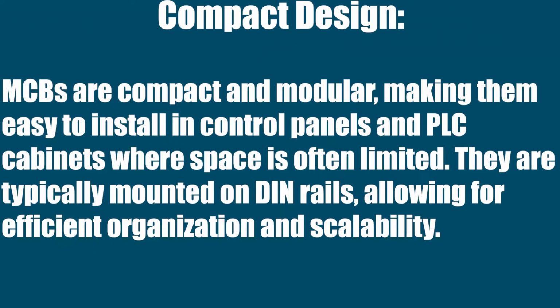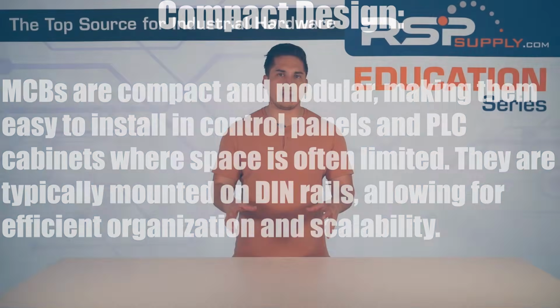Compact design. MCBs are compact and modular. This makes them easy to install in control panels and PLC cabinets, where space is often limited. They're typically mounted on DIN rails. This allows for efficient organization and scalability.